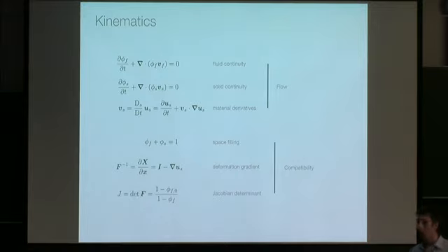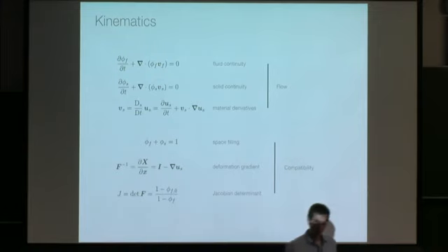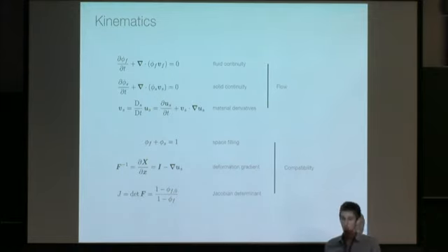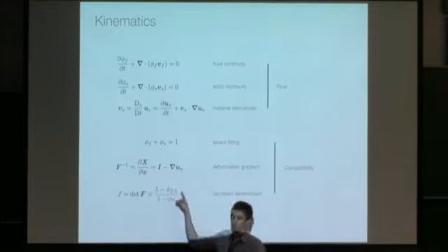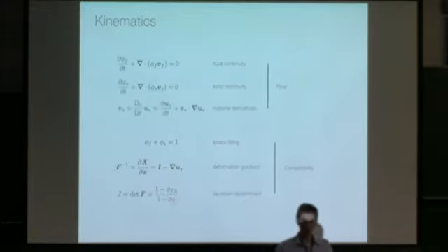And then a very important quantity, or property of the deformation gradient tensor, is the Jacobian determinant, which is just the determinant of the deformation gradient tensor. So that's this thing J. So J is the determinant of F, and J precisely measures how the volume at a point has changed over time as a result of the deformation. And as a result of that, J is directly related to the porosity. So if I know my initial porosity and I know my deformation field, then if I calculate the Jacobian determinant of that deformation field at a point, that has to tell me how the porosity at that point has changed. And this is the statement that becomes a lot more complicated if your initial porosity is not uniform.